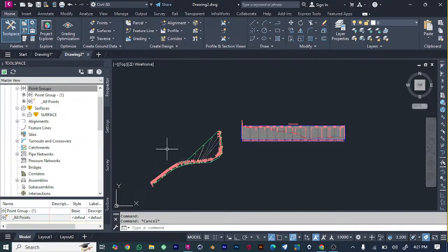After that, the next thing that you need to do, this is everything that you need to get started with AutoCAD Civil 3D. So I will just go and create assembly. Assembly is here, so click here. Remember I told you that you spend a lot of your time in the home tab, and the home tab should be your friend. Whatever I do here is just to create assembly, and we will use those assemblies in our next lesson to create our corridors of this proposed road.